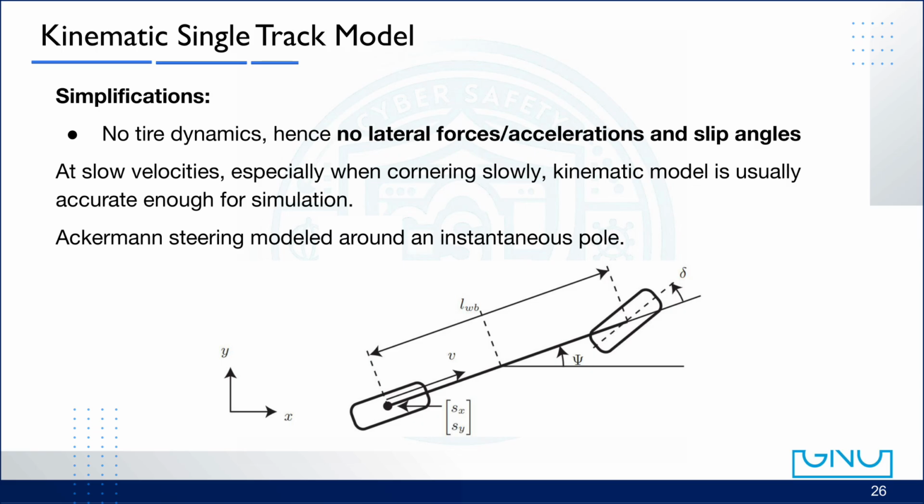First, the lateral force is the sideways frictional force generated by the tire when it resists sliding during a turn. Imagine your car going through a curve. The tires push sideways against the road surface to counteract the outward centrifugal force. That sideways friction is the lateral force. Next, the lateral acceleration is the sideways acceleration that comes from those lateral forces. It's what you physically feel when your body leans outward while cornering. If you've ever felt yourself pushed toward the door while taking a sharp turn, that's lateral acceleration in action.